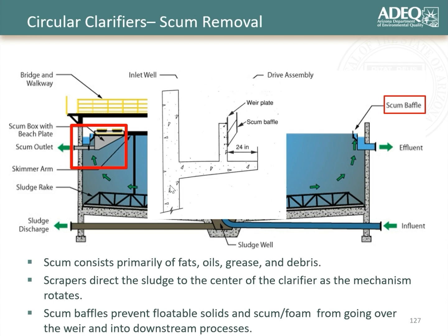In addition, you can have, or should have, a scum baffle right before your weir that is taller than your weir plate. What that allows is that any scum floating on the surface will hit the scum baffle and sit there and not go over the weir.